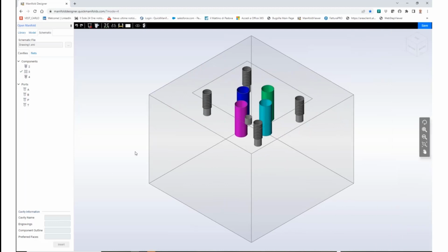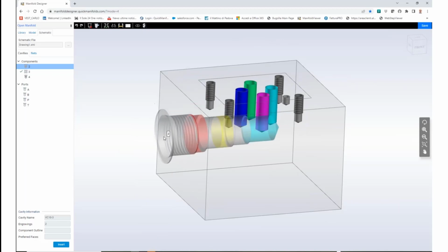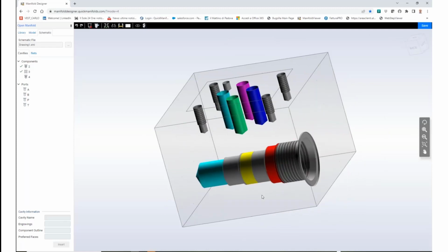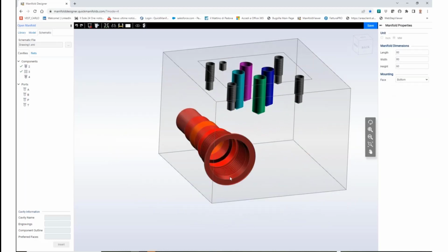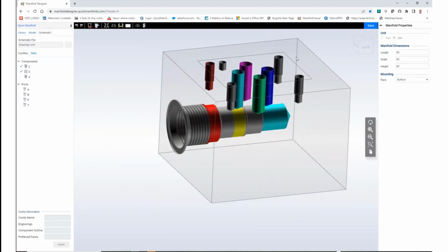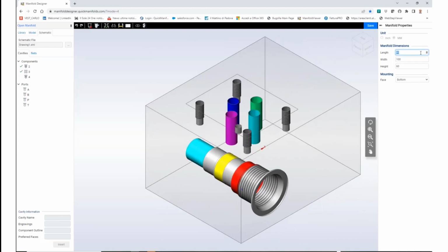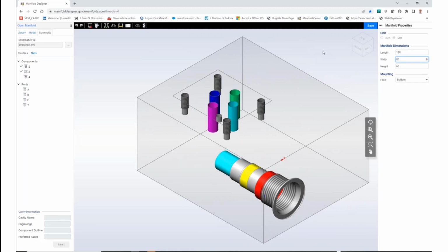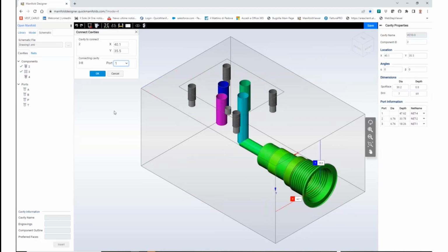Again, we can drag cavities. Let me take this cavity here. We have colors, so we can see which cavities have to be connected with different items. So let me move this. That should be a pressure reducing valve. I put it here. Let me add some material on the width and also on the length, and I remove it here. So I can connect my blue line directly here.